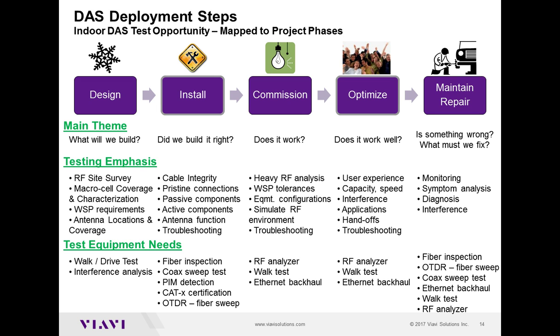Maybe there is not enough RF coverage. Maybe you're doing a DAS because of actually capacity. For example, at a big arena, when the game is going on, the macro cellular capacity may not be enough. So it may have a different rationale, but it truly depends why the DAS is being built. But doing a good benchmark helps you during the acceptance phase, because then you know what your signal levels were before you deployed the DAS for different carriers.